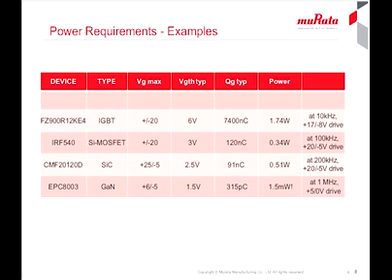Murata has a freely available database of IGBT and MOSFET part numbers with gate drive power calculated for a range of switching frequencies, along with recommended DC-DC converters in a selection of form factors, including through-hole and surface mount. We also have an Excel-based calculator which allows you to put in the device parameters and actual frequency separately to give gate drive power along with peak and average current required from the DC-DC.